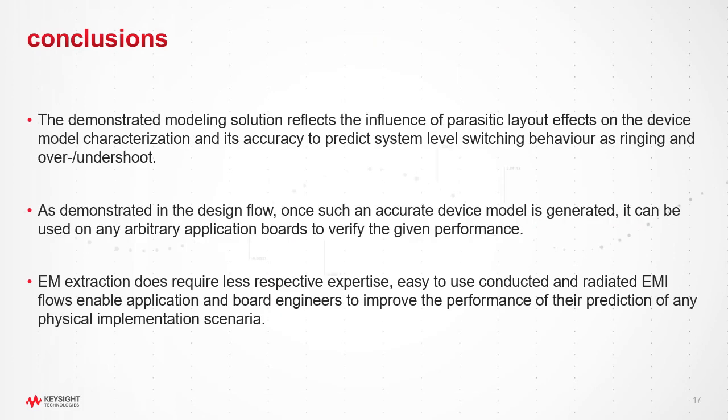Concluding, the demonstrated modeling solution reflects the influence of parasitic effects and how to better predict the switching behavior, the ringing, the over and undershoot of your device and your implementation. The demonstrated design flow is really accurate, and if you can generate such an accurate model, you can use it on any arbitrary application board to verify your performance just by exchanging the PCB model.